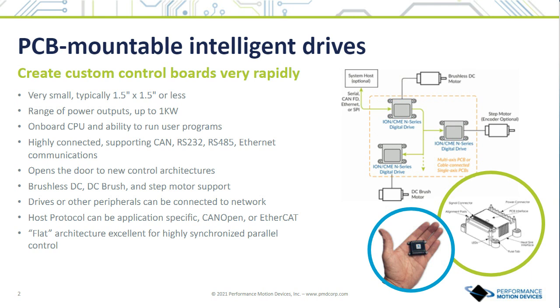And what we're seeing in the medical application, it all depends on the machine design. So they tend to want flexibility in terms of the host interfaces that they connect to. We do Ethernet, serial, CAN, and they also want to be able to talk to several different motors. They want to be able to pick a single motor drive that can talk to all motor types.